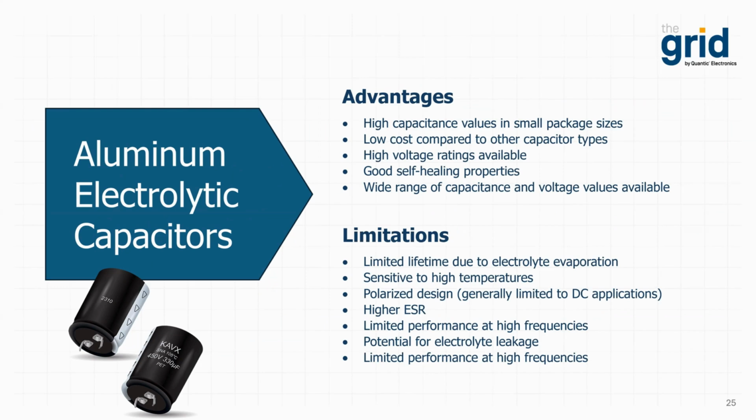Limitations do include the limited lifetime due to electrolyte evaporation. They are sensitive to high temperatures, and they are polarized. In addition, they're known for having a bit higher ESR compared to other capacitor types, and they're limited in performance at high frequencies. And finally, they do have the potential for the electrolyte to leak.